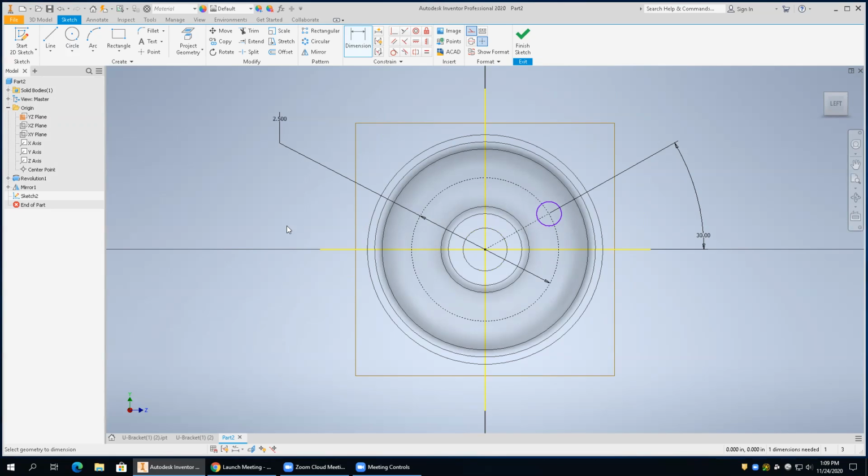You're okay. You just need to dimension it now. So go into dimension. Oh, you know what? You do not have your lines projected. So go into projection. I think we have a Z-axis. Yeah, there you go. Okay, now try to be able to up to that line, do the line, construction line. Construction line.